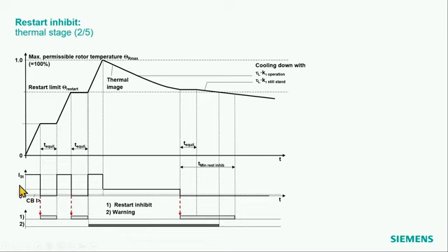Okay, here's another example. Here we go up again in that way. So we start and we switch off the motor directly after the starting, a rather unlikely case, so it's not running at all. Then we see every time we switch off the motor at standstill, I get this restart inhibit blocking signal coming from this equilibrium time. And okay, I move up to the maximum temperature, and from here on the motor is running, and then it's switched off. And you see at the moment the motor is switched off, this restart inhibit signal comes and blocks the close command at the end.